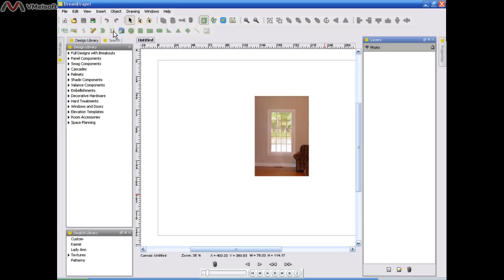And I want to introduce some options to the customer. So in this particular case, I want to add a second layer. To do that, at the bottom of my layers box is the left icon where I can add a layer. So I'm going to do that right now. I'm going to click on that icon and add a layer. And notice at the top I am now on layer 2. So I want to rename that layer.